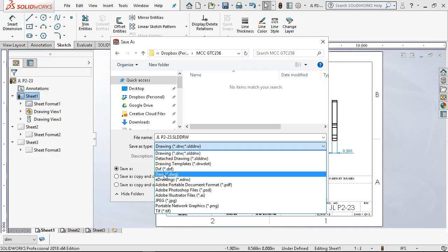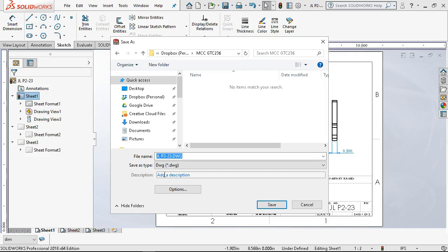So the exchange format versus a drawing, it's kind of a toss-up anymore. It's not as critical. Some of the machines that would import directly would only bring in a DXF because it didn't have as much of the header information, the program information embedded into it.